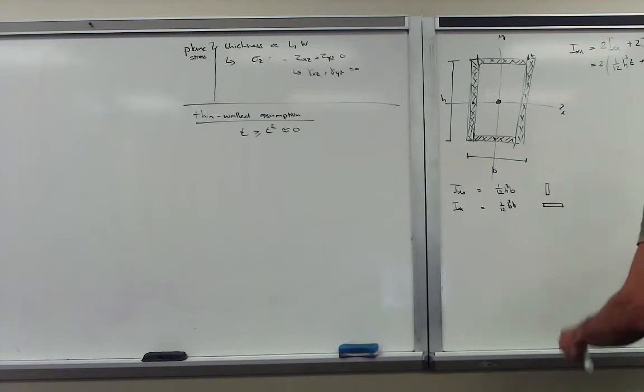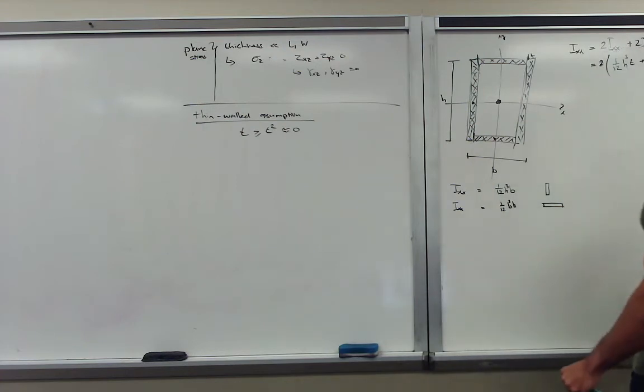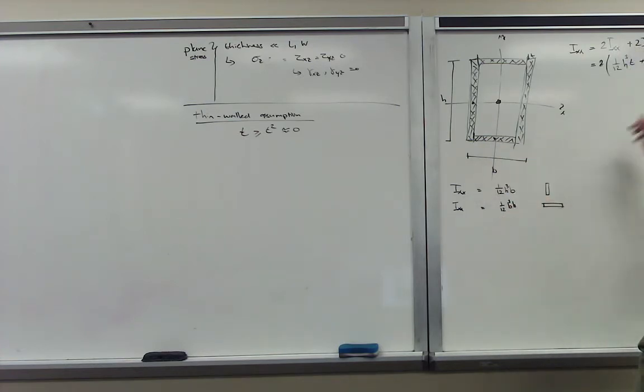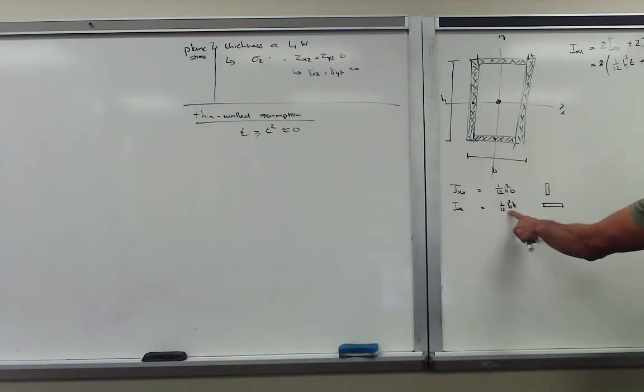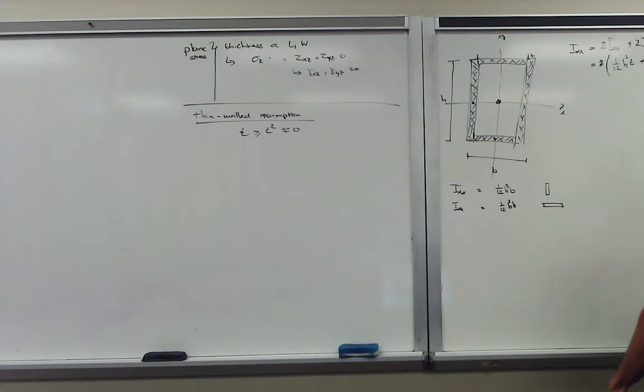So we do the same for the purple section. And we repeat for the purple section. We again have this equation for the moment of inertia. So we get 1/12. So what's the width in this case? It's basically b minus 2t. That's here. That's b minus 2t to the power of 3. And then we get multiplied by h. That's equal to the thickness as well.